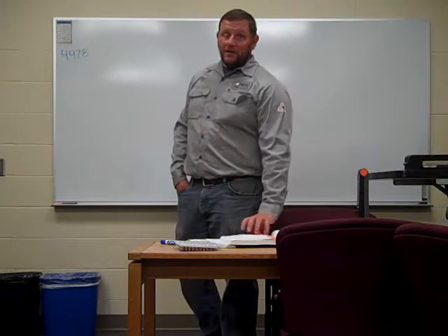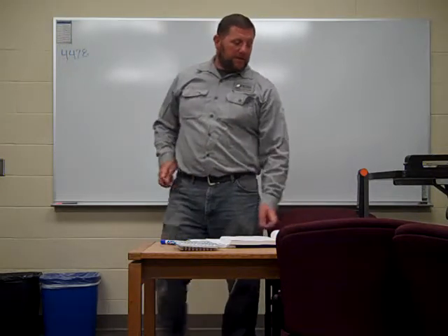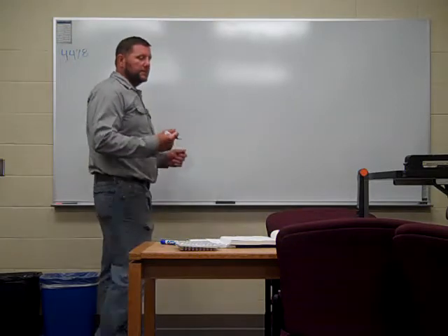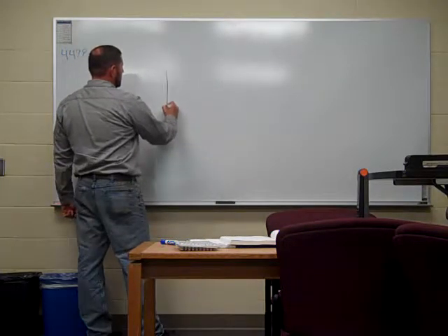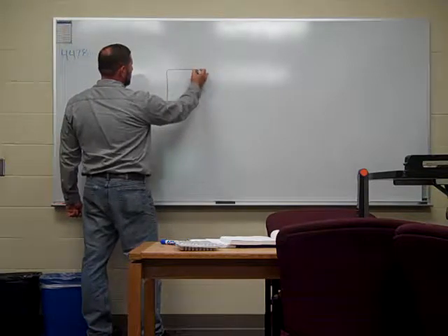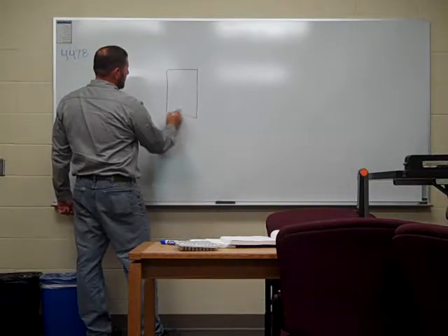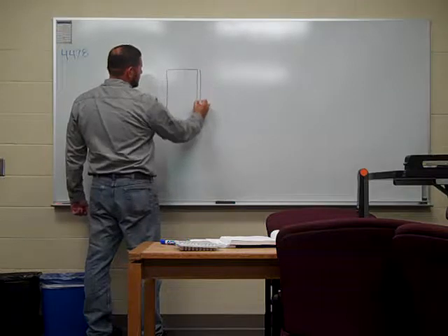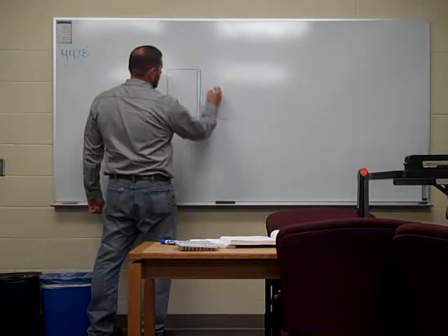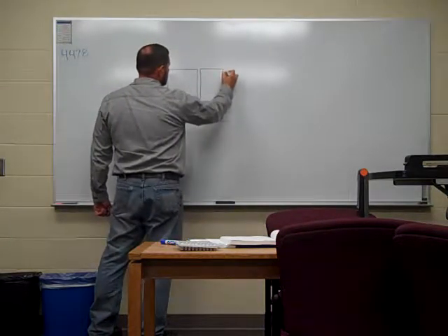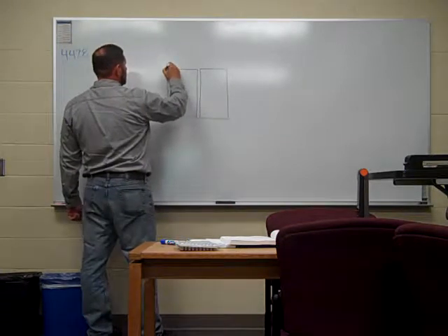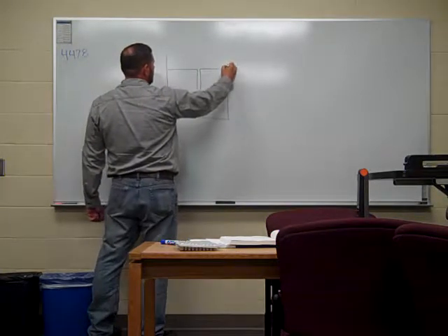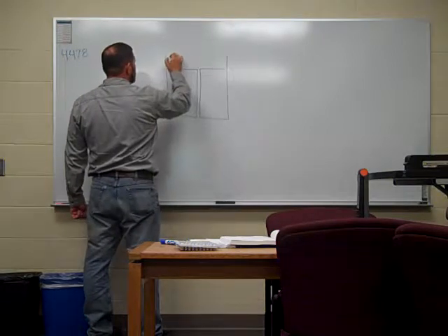As we dive in, go to page 120, and at the bottom left-hand corner, extension and dimension lines are very, very important. The book shows you two basic plates, a typical butt joint. If you've been in the lab, you already know what that is. So here's a butt joint. They give you the overall dimension. Here's my extension line. Remember we went through the alphabet of lines?